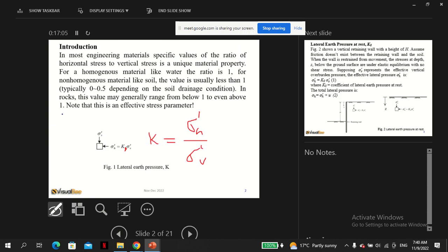You remember consolidation is where we apply a uniform pressure in the sample at the consolidation stage. So this is the value you use at consolidation stage. This value should at least be equal to the sigma p from the 1D consolidation test. It's one uniform pressure.